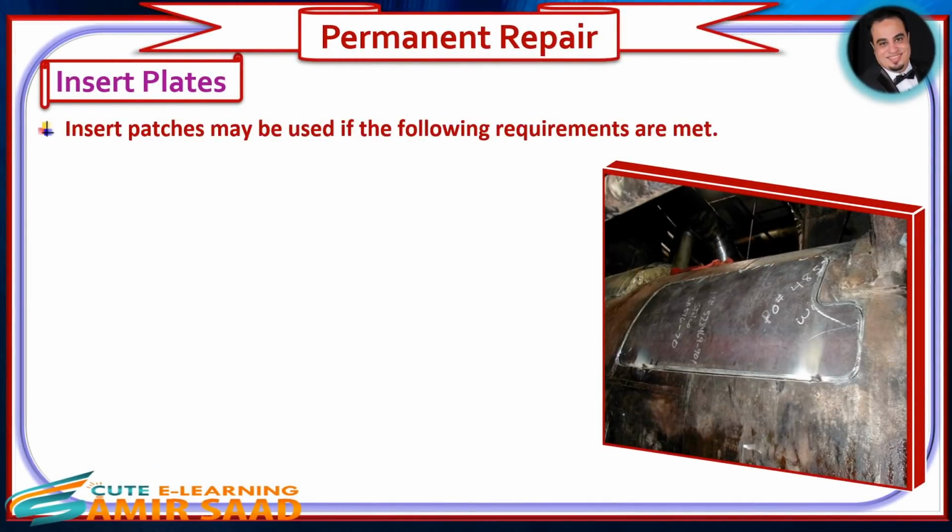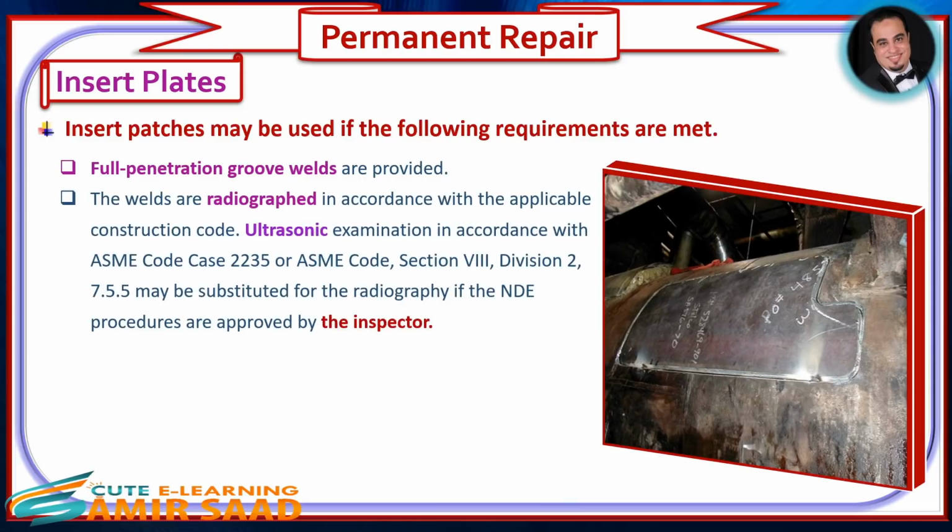Insert patches may be used if the following requirements are met. Full penetration groove welds are provided. The welds are radiographed in accordance with the applicable construction code. Ultrasonic examination in accordance with ASME Code Case 2235, or ASME Code, Section 8, Division 2, 7.5.5, may be substituted for the radiography if the NDE procedures are approved by the inspector.